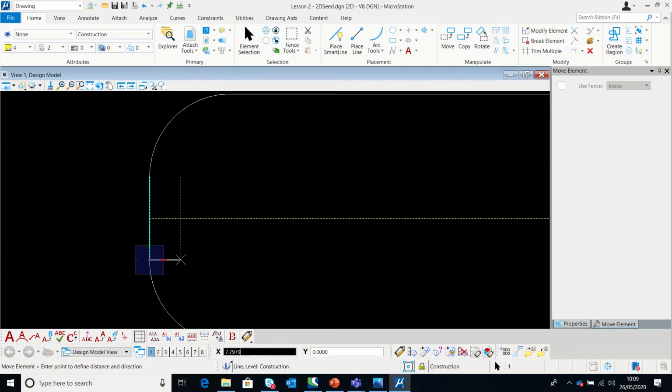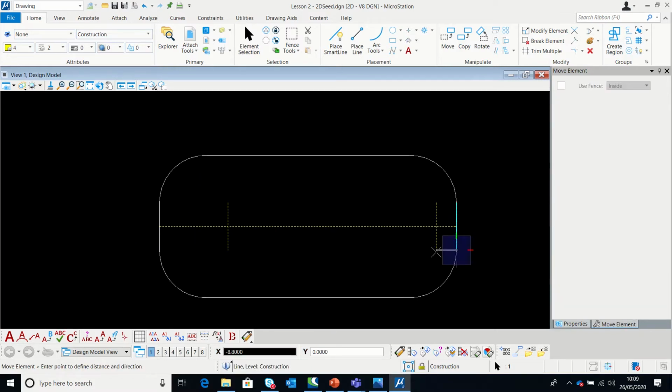You can hit enter, then that way it can lock the plane. So it means now even if you move the mouse, it will be straight. You see now the X box here is active. Now you can type 30, and that will place your line where it's supposed to be. Hit enter to lock the plane, then move it through. Sometimes if you've typed the number, it will lock. So if your last number was 30, it will lock at 30. Now if that's what you want, you just click again using your left mouse. Then once you're happy, you release by clicking your right mouse button.